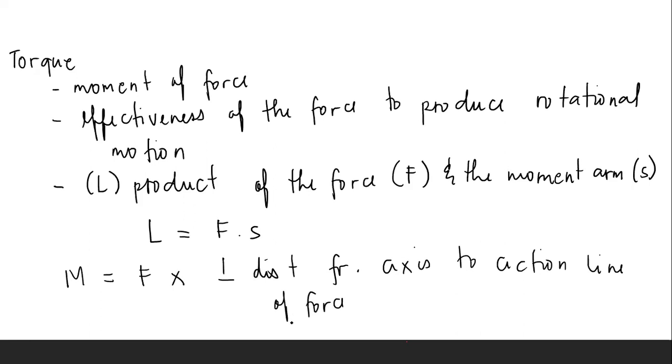Okay, a body is in translational equilibrium if it is at rest or is moving at constant speed in a straight line. It is in rotational equilibrium if it is not rotating or is rotating at constant angular speed about an axis. A system of forces acting on a body produces equilibrium if, when acting together, the forces have no tendency to produce a change in the body's translational or straight line motion or its rotary motion.